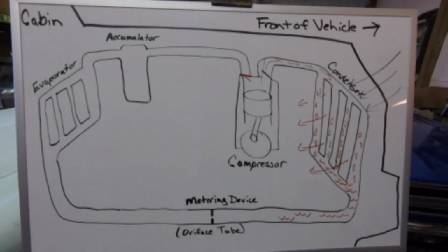The condensation process is critical to the success of the refrigeration cycle. Refrigeration requires mass quantities of heat to be removed from the refrigerant because we are trying to remove heat energy from the air going into the cabin. The change of state from vapor to liquid and vice versa transfers much more heat than if we were just circulating a liquid or a vapor medium throughout the lines.